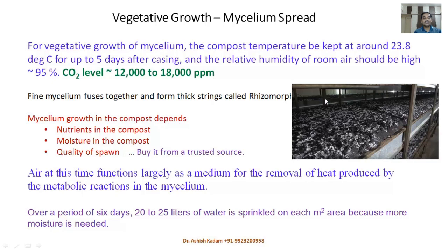Now if you visit the high-tech farms in India, you will not see CO2 sensors. People are not using this technology to its full extent. People are just putting small windows on the walls of their puff panel or insulated panel, and they feel that these small apertures will take care of maintaining the CO2 level.